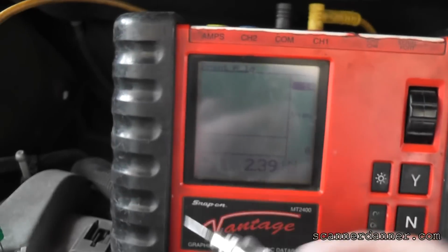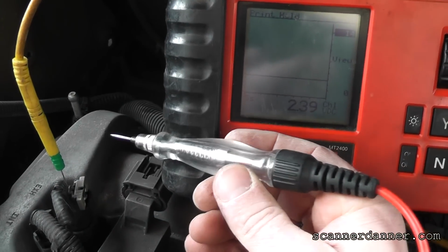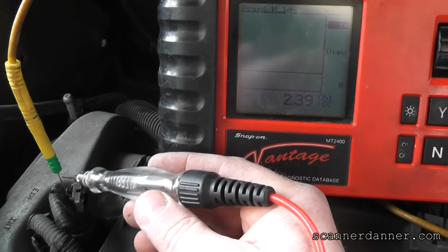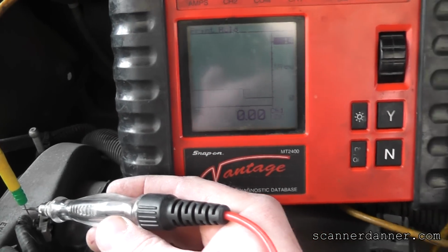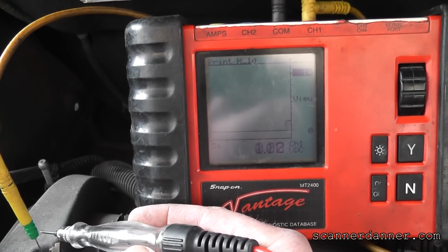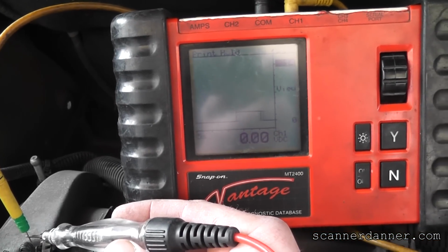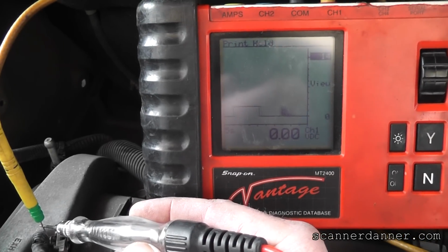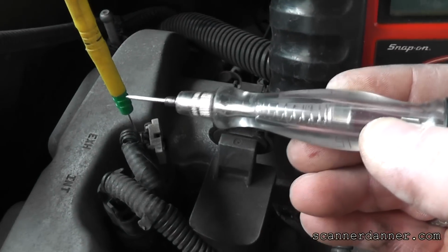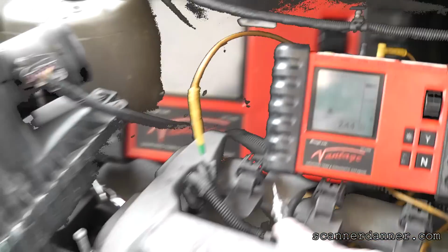And what I'm doing is just taking my test light on this control wire to ground. That's going to pull this voltage to ground. You see that it did. Of course, my light did not light. And there's some kind of circuitry in here. So what I'm going to do is, let me get an alligator clip for my test light.